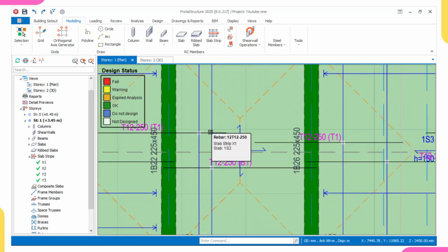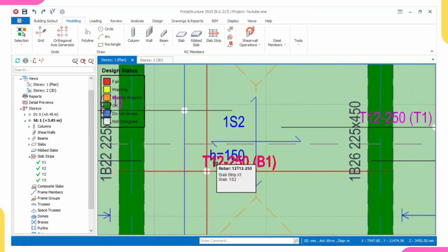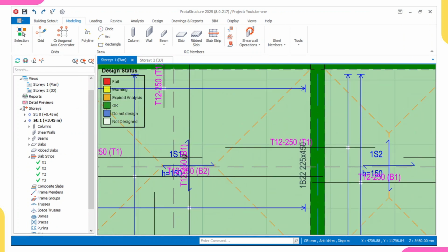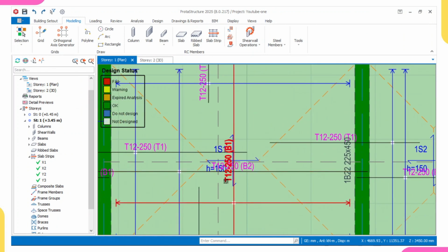Yes, the steel strength, that's the yield strength of this Y12, we assume to be 460, might be 410. Even the Y12 might no longer be Y12, it might be Y10. So that's why in my design, to counter all these things, I'll do Y12 at 200 spacing, even though the design gave me 250 spacing. In all my slabs, the spacing will be at least 200.